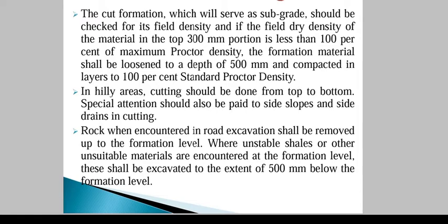In hill areas, the cutting should be done from top to bottom. Special attention should be paid to side slopes and side drainages in cutting.